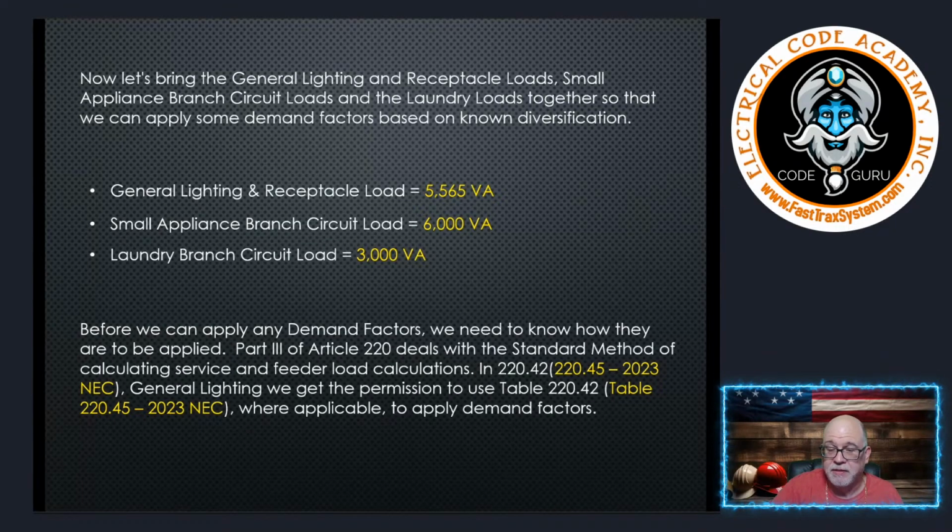Then you don't have to install the receptacle at all, but you're required to have the laundry circuit. And in a single family dwelling, you're required to install the laundry receptacle outlet. I believe that is in 220.52(D), if I'm not mistaken.